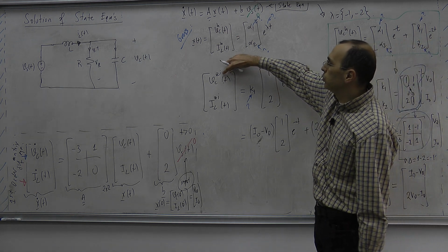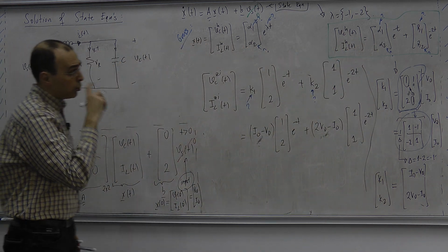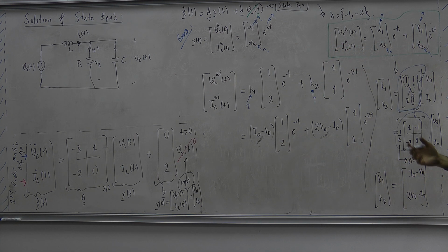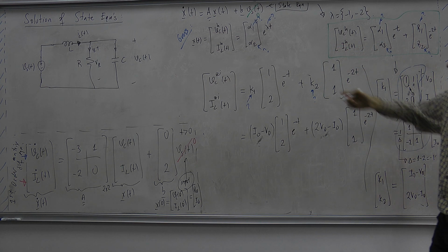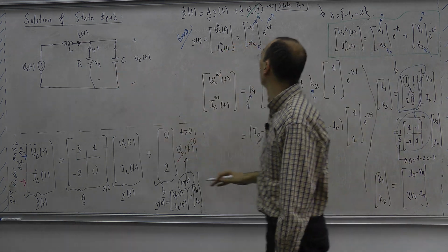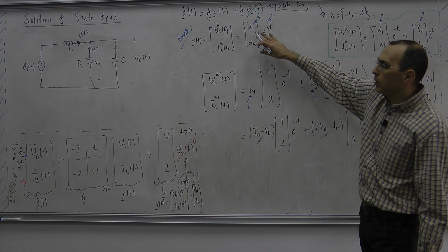And this is a zero input circuit solution. Zero input circuit. Again, one more time. Many students confuse zero input solutions with the homogeneous solutions. Of course, they are looking alike. But zero input is the solution of a circuit, a physical circuit that you construct. Homogeneous solution is something like a theoretical tool.